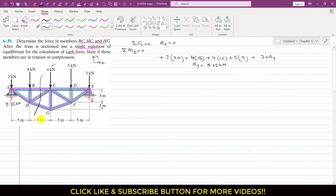So I will pass an imaginary cutting section like this, and this imaginary cutting section will divide this whole truss into two parts, right? And for our analysis, we can consider either of these parts. I will consider this part since I know the reaction at point A. If I consider the other part, I have to find the support reaction at this point E. Since I know this A support reaction, and we have fewer members towards this side, I am going to use this part of the truss, right?